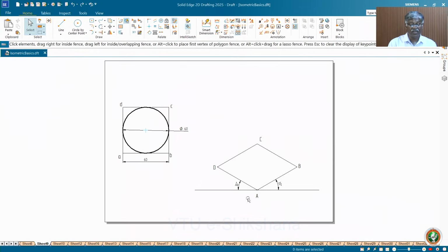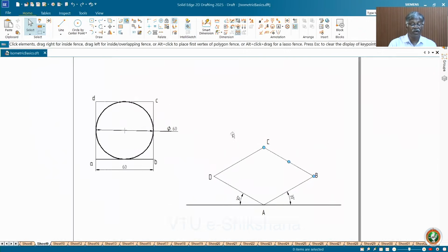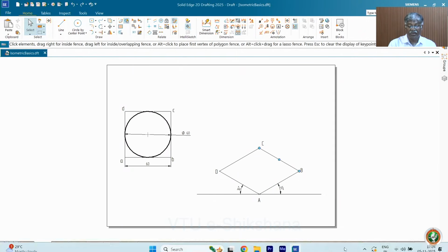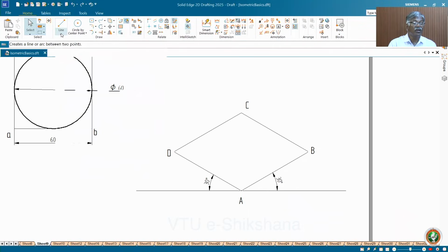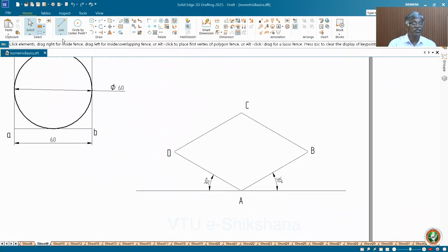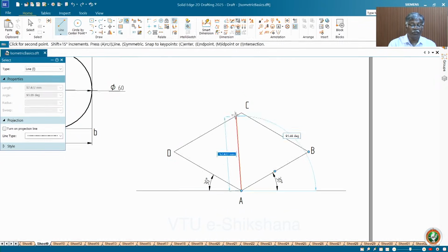Now what is the procedure? Four centers method. How to identify the four centers? Now you have to check these sides, midpoints of the sides connect to opposite. Now I will do it. Okay, we'll do that job now. See, draw lines joining corners with opposite midpoints of the opposite sides. That is the procedure. Do it carefully. Now again take this corner and opposite sides' midpoints.